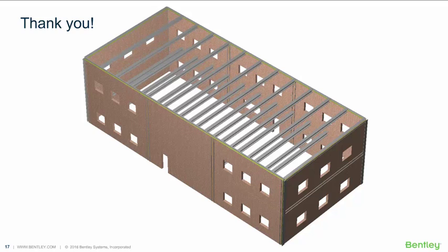I'll go ahead and answer this in the context of concrete. What you're looking to do is place a column at the ends of the walls, optimize the steel in those end columns, and leave just a minimum amount of steel in the wall that connects them. RAM Elements is very good at this.